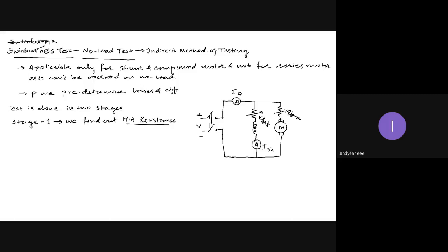So by observing the line current of the load, in the case of transformers and generators, we indicate the load condition, the load factor. But in motors, we can't do that, because motors draw line current from the supply even in no load condition, because they have to overcome the rotational losses. Rotational losses, or mechanical losses, are the major losses that have to be overcome.